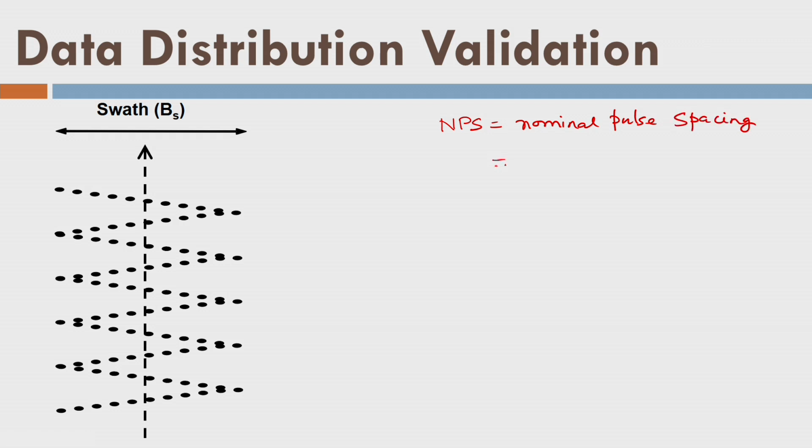And that is nothing but 1 upon the root of the data density, and I will tell you the reason. See, the data density is given in points per meter square, that is the number of points in a unit square area. Now I want to find out how much area is represented by each point of laser data.